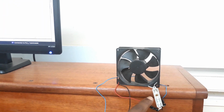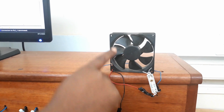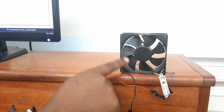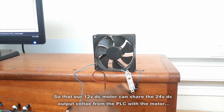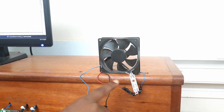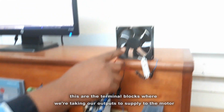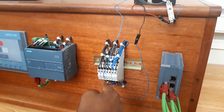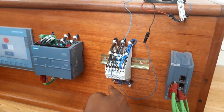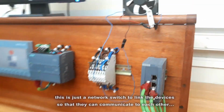The motor is in series with this light because the output voltage is 24 volts DC and this motor is 12 volt DC. So it is connected in series with this LED light, which is also 12 volt DC, so they can share the voltage together. These are the terminal blocks where we are taking our outputs to supply to the motor. The motor is connected from the coils, from the K0.2 output there, as indicated. This is just a switch to link the devices so that they can communicate with each other.